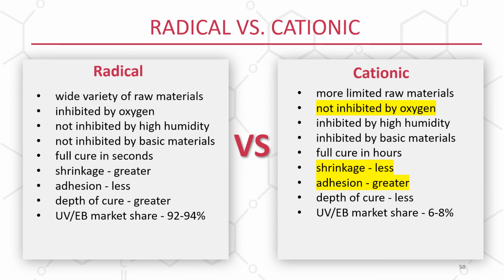And because this webinar is focused on cationic curing, I like to bring up why, in my exposure to and working with cationic cure over the years, it's these three reasons: lack of oxygen inhibition, low shrinkage, and greater adhesion, which has drawn a lot of formulation systems to use cationic curing preferably over free radical curing.